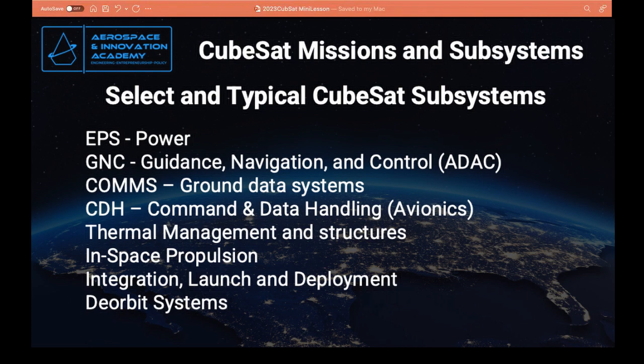So that takes us to our last couple of items. When you integrate your spacecraft, you can't just staple it onto the side of a rocket. You can't give it to an astronaut in a duffel bag. It has to go somewhere. If you're going to deploy directly from the rocket, you're going to use some sort of P-pod, some kind of deployer. NanoRacks makes a deployer. Tyvak, I believe, had the P-pod. But the bottom line is, if you're going to be injected into space, either from underneath a rocket down near the rocket bell or up top as on an ESPA ring, secondary payload ring, you've got to be integrated.